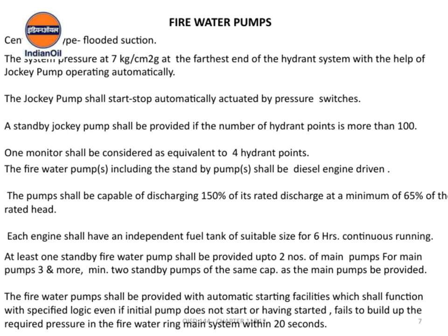This system should operate based on a specific logic, ensuring that even if the initial pump doesn't start or fails to build up the required pressure within 20 seconds, the standby pump can take over seamlessly. All fire water pumps, including the standby units, should be diesel engine driven for reliability.